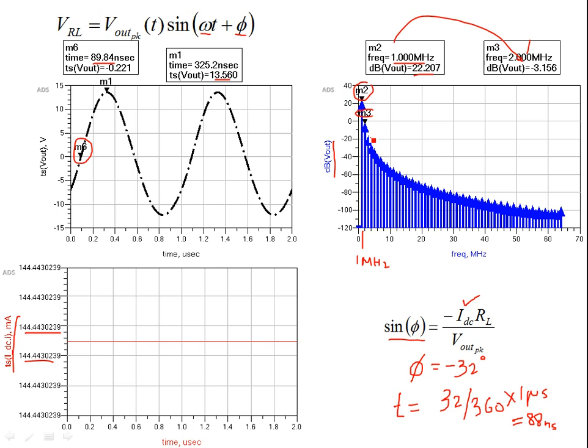Okay, so the third harmonic and fourth harmonic up until the 64th harmonic, these amplitudes are not important. They are not contributing much to the output time domain signal. They have a very small magnitude. Even the second harmonic is 26 dBs down the first harmonic, so the 32nd or 35th or 40th harmonic, they don't count much.